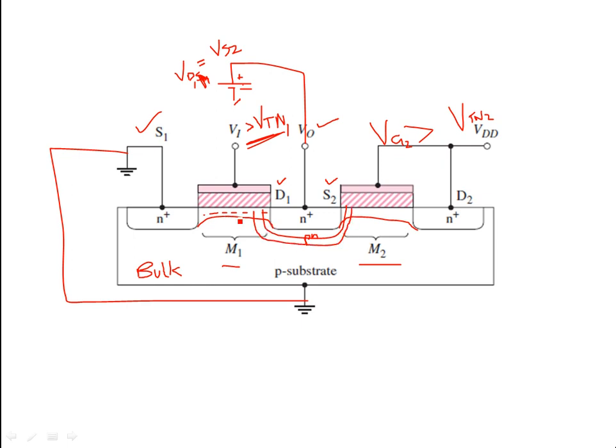There is already a reverse biasing over here as well, because both NMOS devices have their n-doped source and drain regions on a p-type substrate. But over here the depletion width is more, due to the positive electric field applied at drain D1 and S2.